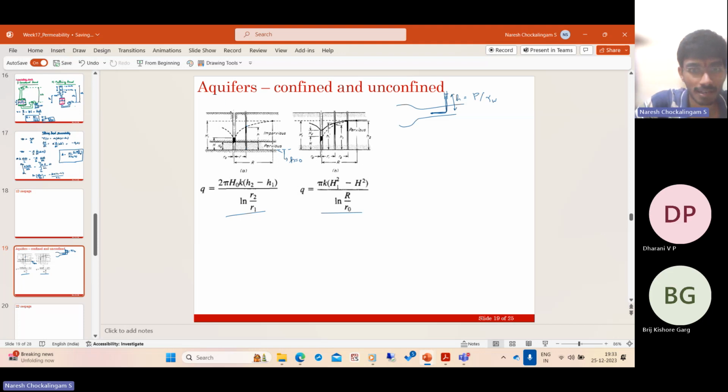So suppose we drill a well here, and we are pumping water out at a constant flow rate of Q. And somewhere away from the well, you drill another observation hole. And when we drill a hole, immediately water rises because it has to equilibrate with the atmospheric pressure. So if you take the water interface, this will be at some pressure.